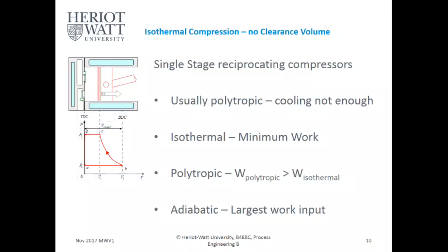Just a note, rotodynamic compressors usually operate adiabatically because they move so quickly, and single-stage reciprocating compressors usually operate polytropically because of the low speed. That's the kind of thing that might come up in the exam.